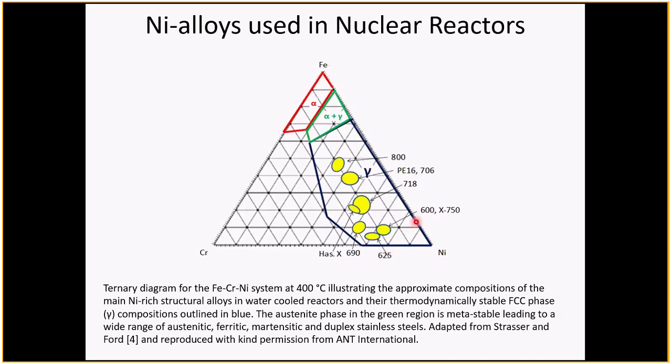So even though it's known that Inconel becomes very brittle after a few years in a reactor, people still tended to use these materials in the reactors and just shrug their shoulders after 5 years when the things rattle themselves apart and say, oh well, we'll replace it and put a new one in. So 690 is used in steam generators.